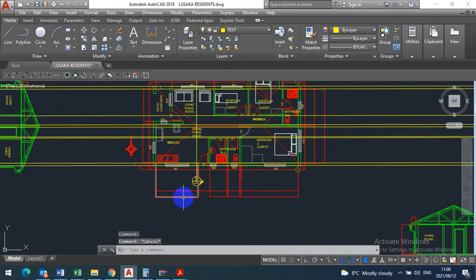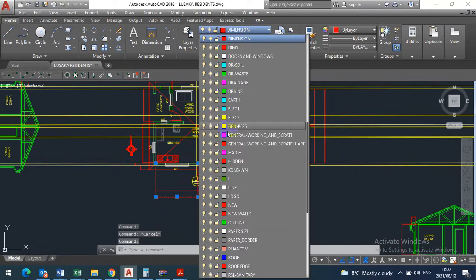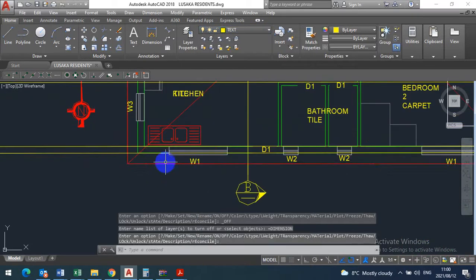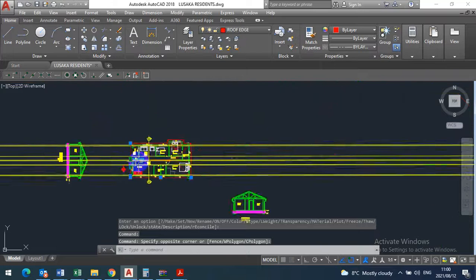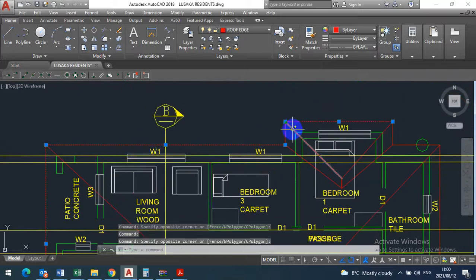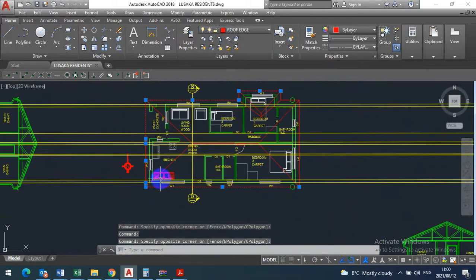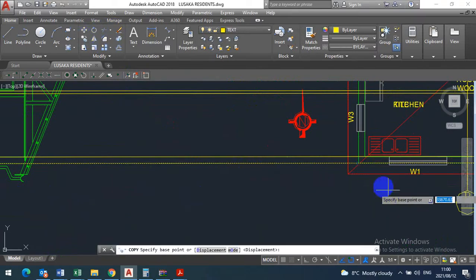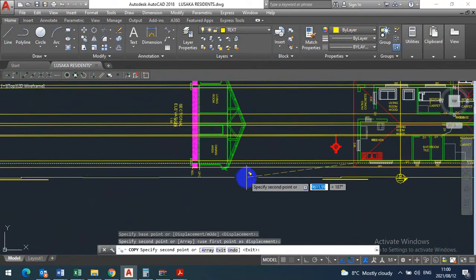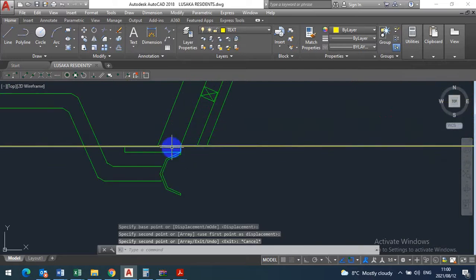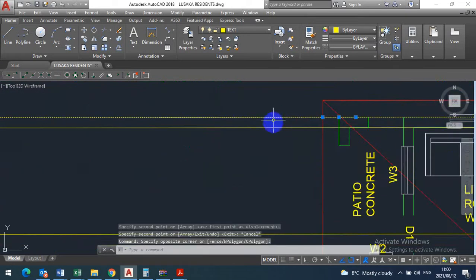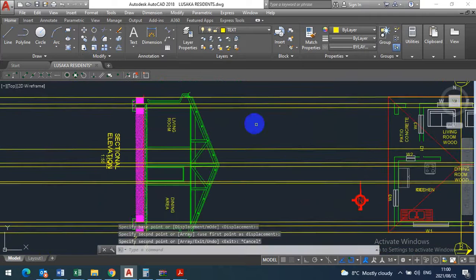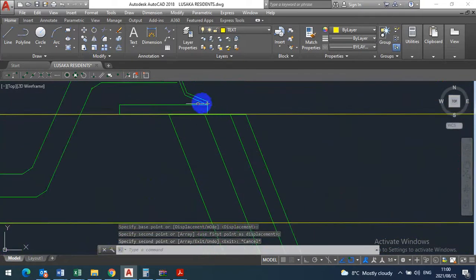Okay, then I'm going to switch off the dimensions. There's a reason why I'm switching off dimensions, because I've got the roof edge. The red lines that we see here, what I'm highlighting here, this is the roof edge. And if you follow the roof edge, let me copy this yellow line. It must be in line. You can see the way it's lining up, exactly where the roof ends, which is also the same here. Copy from here to the roof edge. If you follow nicely, that's exactly where the roof starts, and that's the fascia board here.